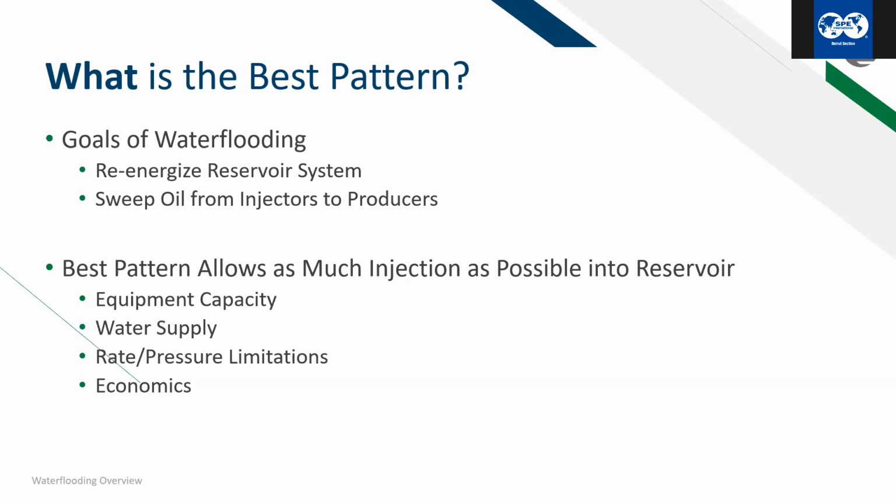There's no one right answer. It really depends on what's going on in your reservoir and what's going on in your field. You have to take into account your surface equipment capacity, what kind of water supply you have, if you have any regulatory limitations, and then also what's economic. So I may be able to drill 50 injectors for 10 producers, and that's going to inject a lot of water, and you're going to be able to re-energize the system. But is it economic to do that? And that just varies depending on the field.